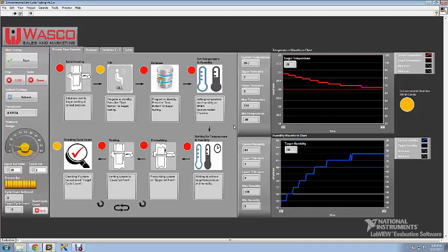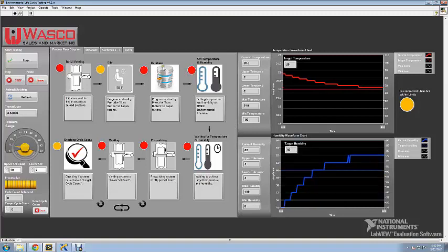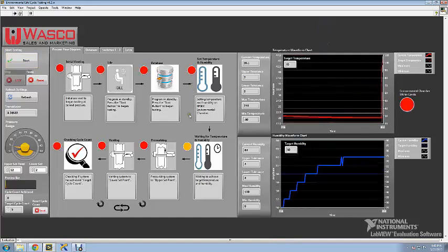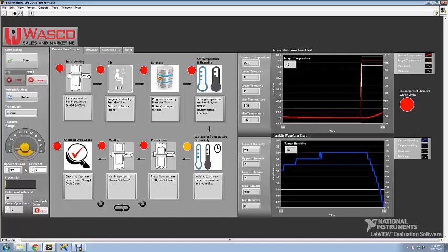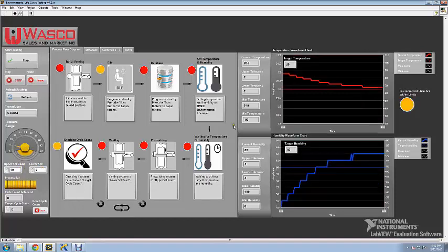Here we can see the program in action. As you can see from the two graphs on the right, temperature and humidity are constantly being monitored. This gives the program an artificial-like intelligence so that if temperature and humidity ever fall outside of the given tolerance zone, the program becomes self-aware of the issue and then corrects itself. Along with temperature and humidity, pressure is also constantly being monitored. This is essential because when capturing the switch's actuation pressures, we are going to need the transducer value.